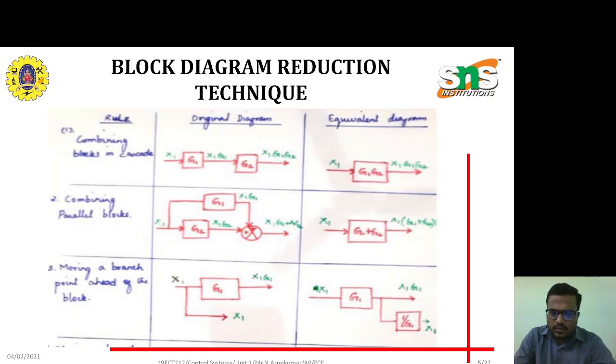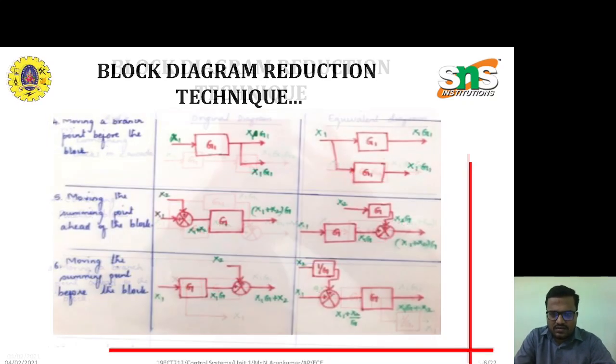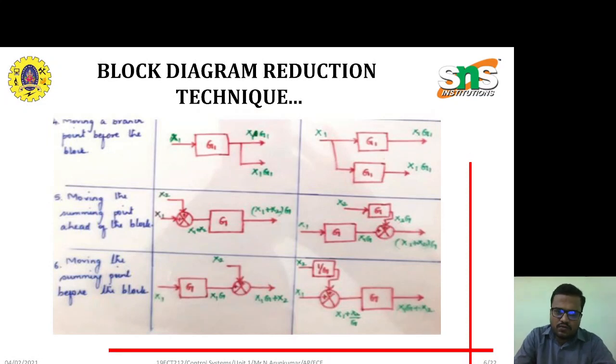Next one is combining parallel blocks. If the blocks are in parallel, then we take it as G1 plus G2, the addition. If a branch point moves from one branch to another, we have to consider it like this, because we move X1 ahead of the G1 block, so it comes as 1 by G1. Next one is moving a branch point before the block. The branch point is after G1. This branch point can be moved towards G1 by including a G1 block, because it is moved past G1, so we have to consider the G1 block again.